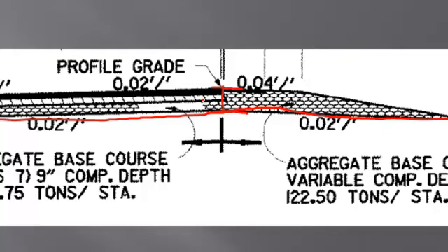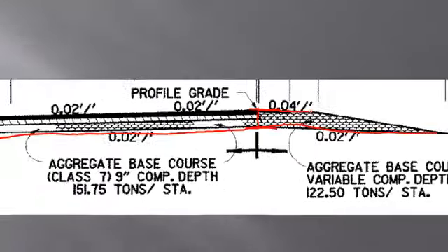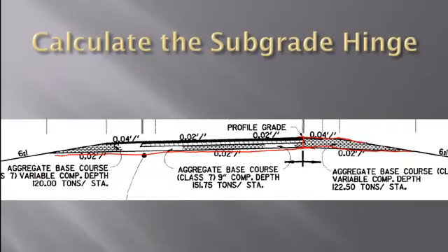The thing is, you need to have your finished surface built because these foreslopes need to be in, so the software will project the subgrade out to that all-important subgrade hinge. You need to calculate it by using the software, but there are times in tangent sections where you can come down like we did in a simple subgrade and calculate this and give yourself a horizontal offset in a tangent section for a subgrade.